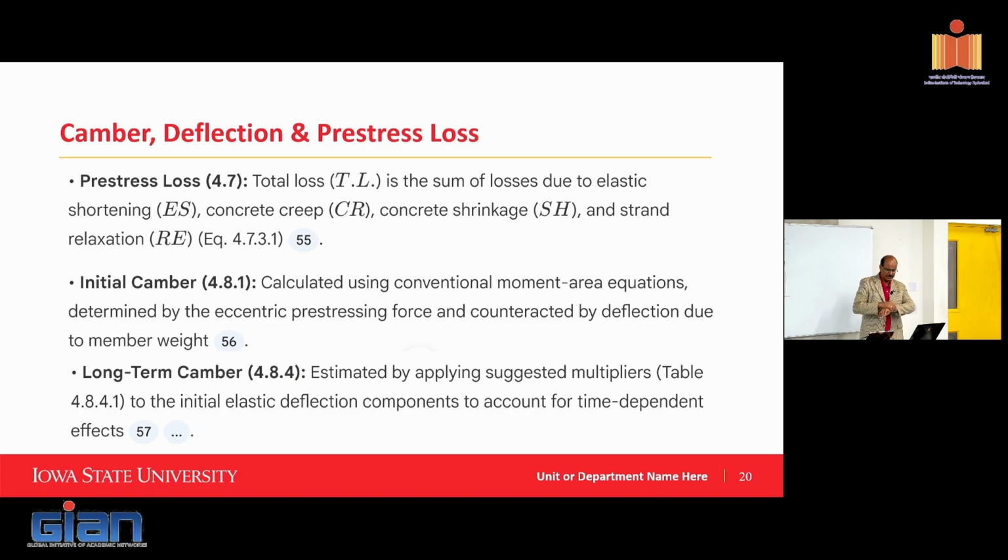Camber, deflections, and prestress losses. Again, we touched on that briefly. Prestress losses is a huge component. I think if you're doing prestressed concrete, I assume your homework is already asking for you to assume them. Yeah. So prestress losses can be as much as 20-25%, depending on the type of prestressing you do. So it's a significant amount of losses, right?